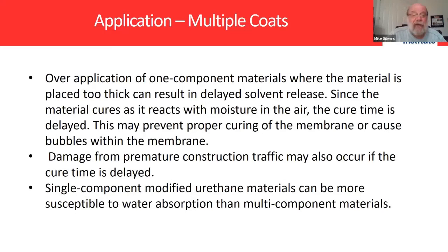If it stuck and you had to scrape it off with a scraper and it was still stuck to the concrete, some of it was ready to go. It's a lot harder to do that with these chemicals, and I've actually heard of some guys that still carry around a little thing that they can heat up with asphalt to test concrete, because it is a real good field test of whether the concrete is dry enough or not.